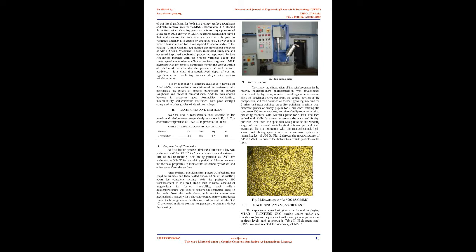Jayaraman et al. investigated the effect of machining parameters on surface roughness for AA6063 using Taguchi integrated Gray Relational Analysis, and found that the feed rate provides the primary contribution and influences surface roughness most significantly. The increase of feed rate increases the surface roughness. Suresh et al. studied the effect of turning parameters on Al/SiC/GR hybrid composites using Gray fuzzy and noticed 2 key observations: Al 10% SiC-GR provides better machinability compared with AMCs with 5% and 7.5% of SiC-GR, and fuzzy logic improved the performance index.